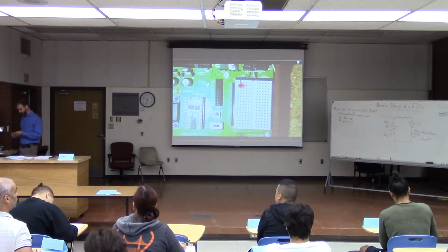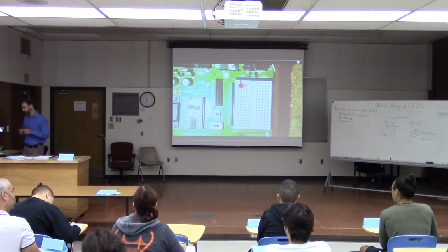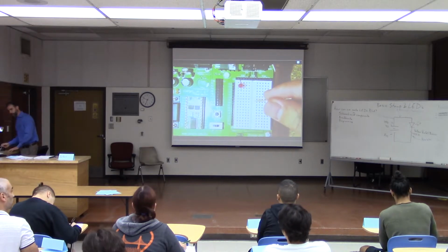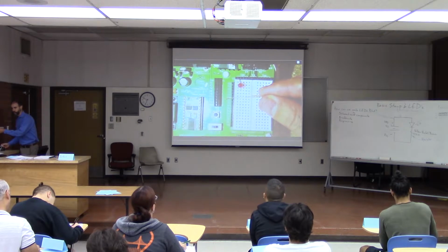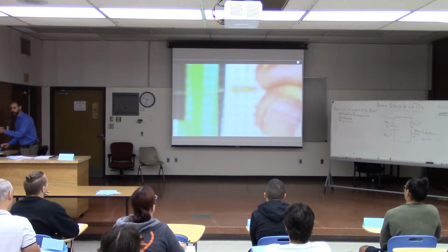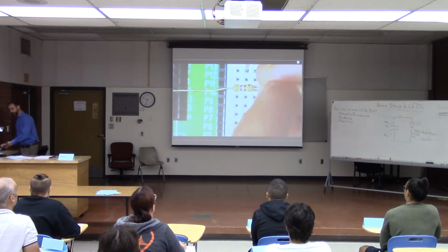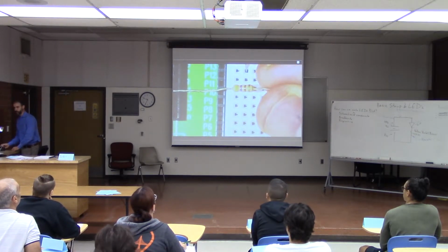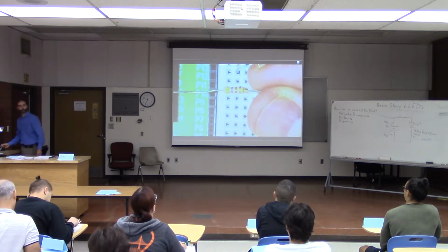Now these bands are very small and the colors are kind of faded sometimes, so it's hard to see. You have to look very, very carefully in order to pick them out. But we can zoom in on this, and hopefully you can see what it's supposed to look like. There, so it's supposed to be yellow, violet, brown. And then there's a gold band on the right. We'll talk about that later. But the main colors are yellow, violet, and brown. Okay.